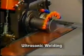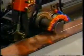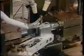Ultrasonic welding is a method of producing lap joints by high-frequency vibratory energy and moderate force. This induces interatomic attraction and metallurgical bonding at the weld interface surfaces with relatively little heat. The workpieces are clamped between two welding tips called sonotrodes or jaws.